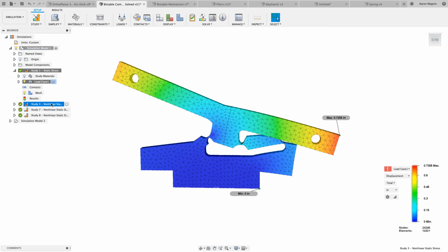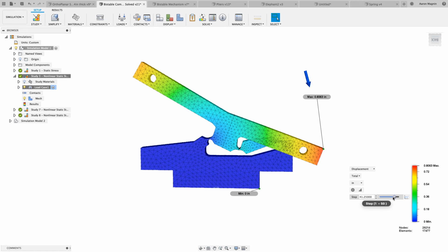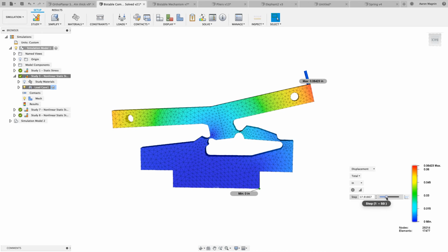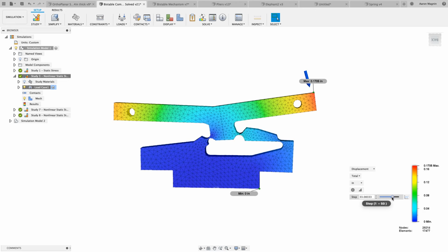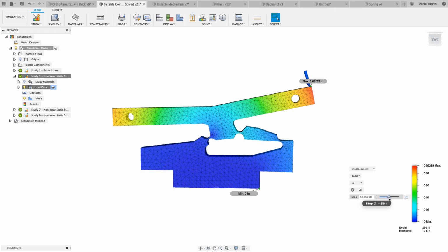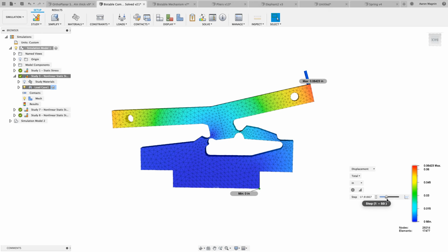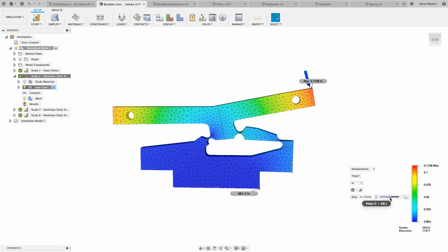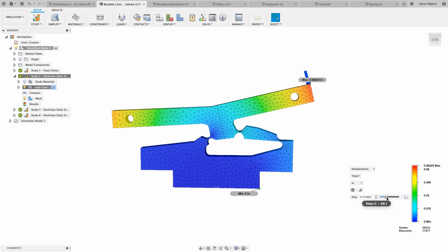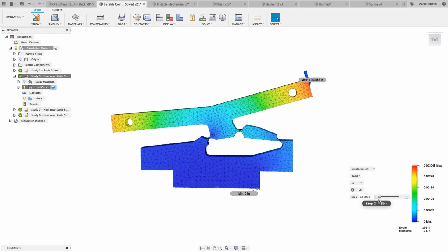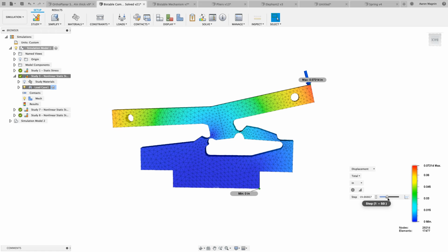So instead, I could have gone and done this with a nonlinear study, and here was the first go that I did. I believe this is the actual displacement, so I'm just going to verify that real quick. As we get into the 50th step here, you can see it goes from moving very slowly. And one thing to note is that with the nonlinear studies, the load is just being incremented up per your solution domain. So over the 50 steps that I've solved this over, it's just slowly adding a little bit more weight each time. As it gets towards the end here, it's going to snap.